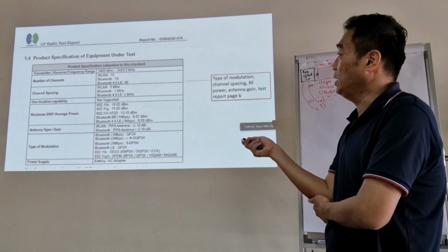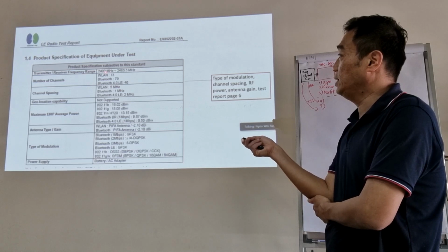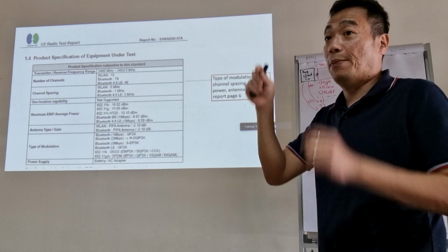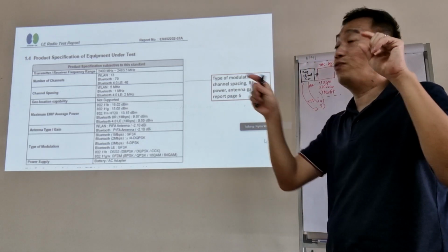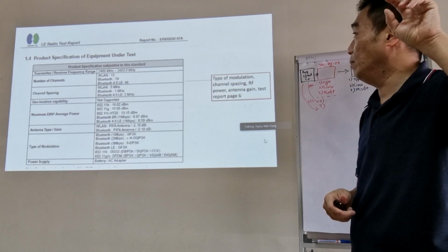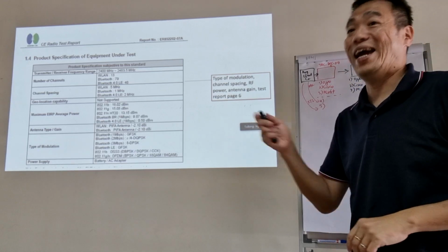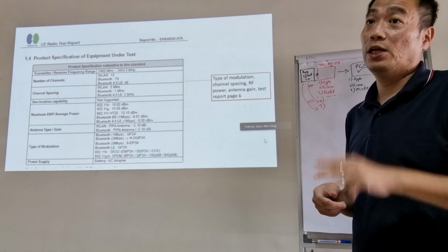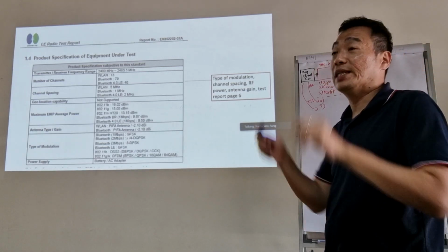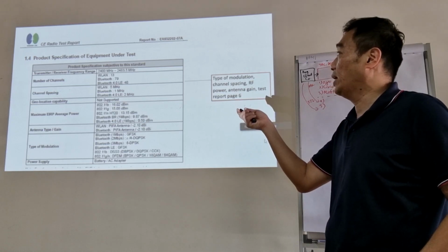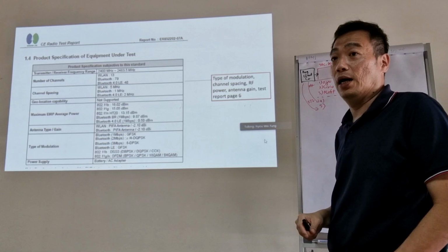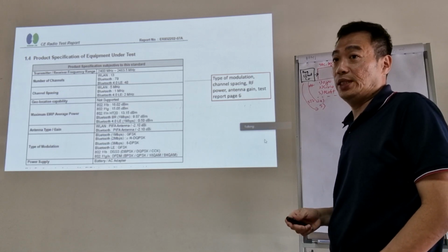So in this report it will have all three, 1, 2, 3 reports. So you check back how they come up with the test, the RF test. So for this standard itself, they probably have wireless LAN, Bluetooth, and another Bluetooth 4.0 low energy. They probably have 3. That's why, for the added test report, you have to add the RF test. Using the same 300, 328, it already has 3 types of different short range frequency.